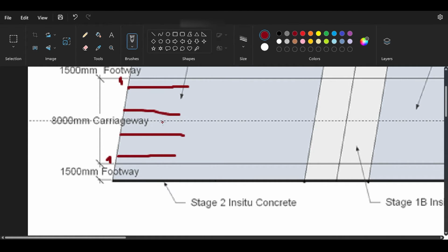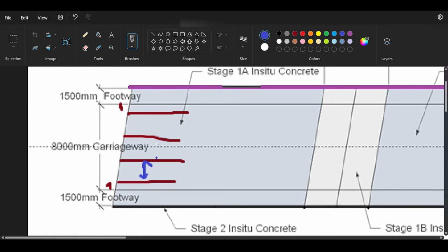Those are my inner beams. 1 here, 1 here, 1 here, and 1 here. And you can see the center to center spacing is 2 meters, and that's perfectly fine. For the edge beam, it's going to be different because I have 1.5 here. So it's going to be iffy. How can I do that? I think I will put an edge beam here. Let me draw it in green. This is going to be my edge beam. And it's going to be maybe 1 meter from this side and half a meter here. Yeah, I think I will do that.